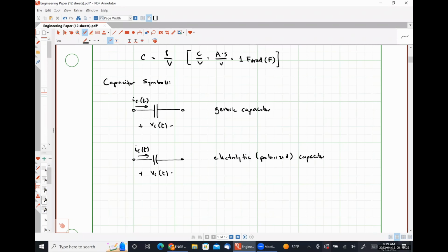That's actually a groove cut in the metal so that when or if that capacitor bursts, that plate can deform without letting all of the stuff inside the capacitor, which could be dangerous chemicals, out. Okay? So typically speaking, if you see a cylindrical style capacitor, your best bet is to treat it as if it were an electrolytic capacitor. And there's usually a black strip on the casing that tells you which leg is the negative leg. It's also the shorter leg because they usually have a long leg and a short leg as well.